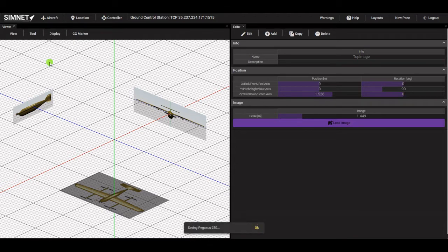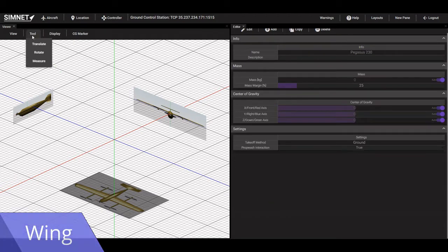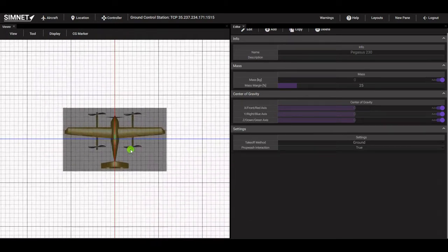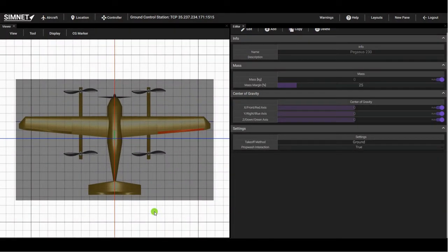We will now begin modeling the main wing. In SIMNET, the wing geometry is parametrized using multiple segments, each one with its own length, chord and sweep, twist, dihedral, and airfoil. If the wing has control surfaces such as ailerons or flaps, each control surface must be placed within a single segment. Therefore, for this wing we will use 3 segments, one for the central span of the wing, one for the span with aileron, and a third for the wingtip.